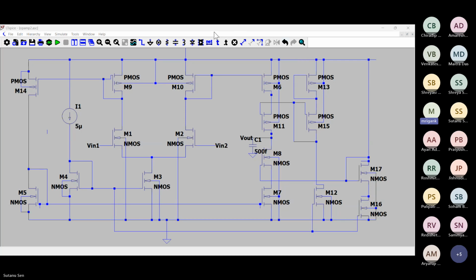already shown a big gain, and your only issue is that the input required DC difference is pretty significant, and bandwidth is low. Compensation has been done to get the phase margin required. Transient value is also coming. Whatever the AC response is showing, the same transient response is also coming. So these things are done. Of course, now this op amp can be used for doing useful things.